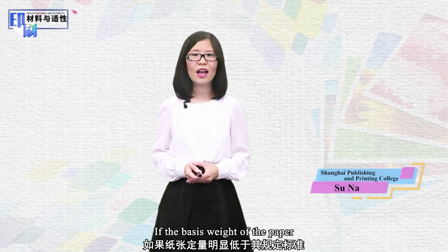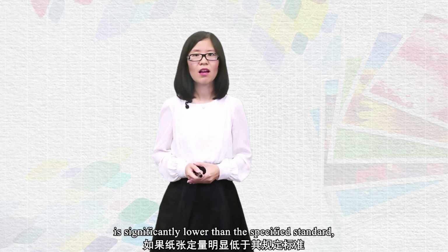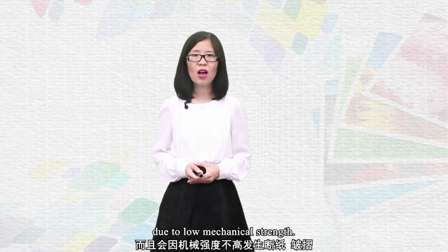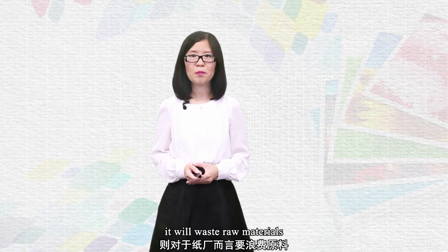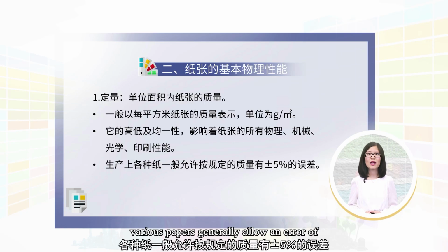If the basis weight of the paper is significantly lower than the specified standard, it is not only prone to ink penetration, but also prone to paper breakage and wrinkling due to low mechanical strength. Conversely, if the basis weight of the paper is too high, it will waste raw materials and increase paper-making costs for the paper mill. In production, various papers generally allow an error of plus or minus 5% from the specified mass.